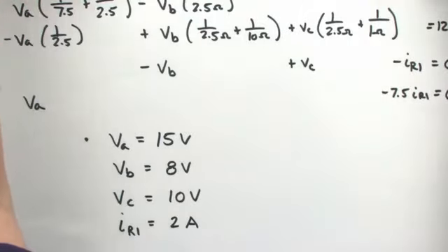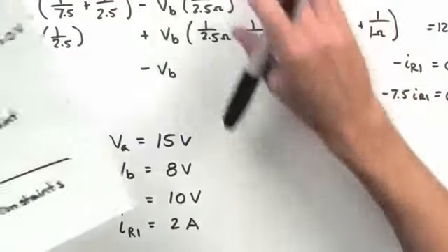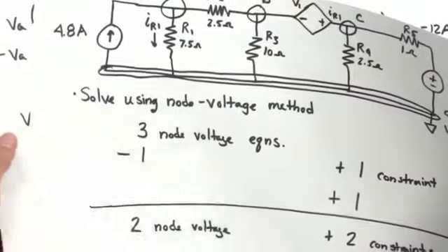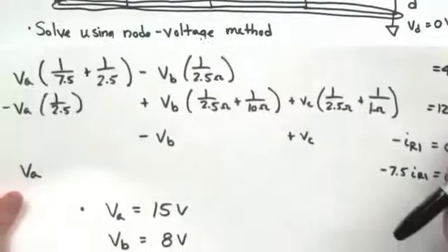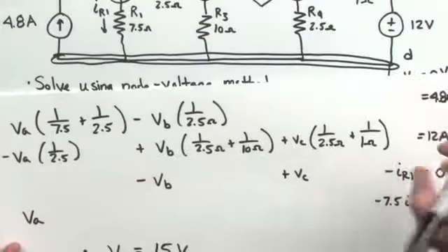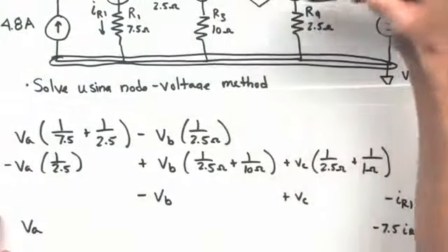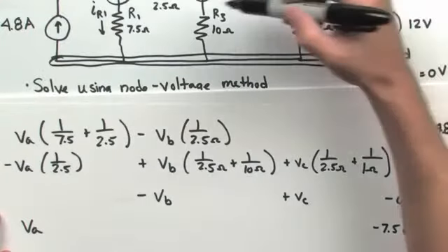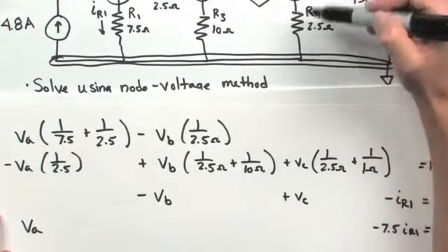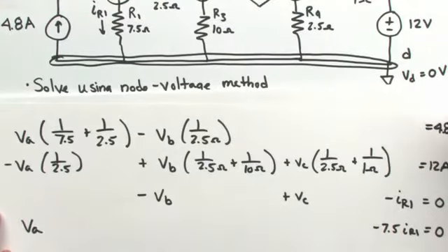So again, by developing those 4 simultaneous equations, now we have completely solved the circuit because we know the voltages at the primary or the essential nodes. From those essential node voltages, we can calculate the current through any of the branches in the circuit.